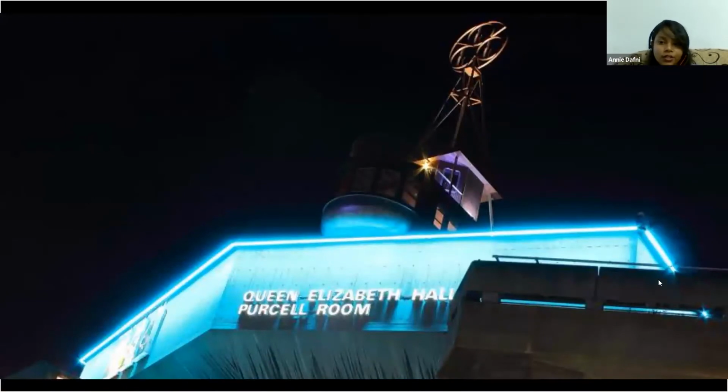So this is actually a real installation of the exterior linear graze fixture, and you can see that it creates a nice gradient effect. And exterior linear is most suitable for textured walls because it will bring out the textures and the unevenness of the surface, because these fixtures are generally placed very close to the surface that you're lighting up.